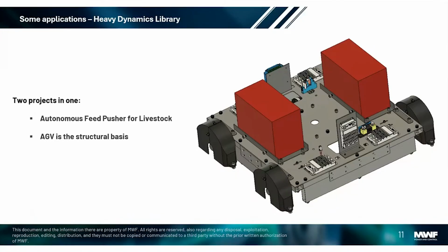During the design of this platform, we had to accurately define the amount of power needed to drive the wheels, and to analyze the trafficability as well by checking whether the lateral slippage was too high or not, and whether the control system would work even in the presence of many uncertainties like the position of the